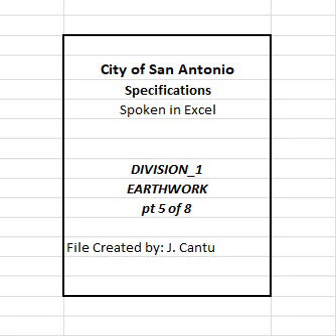5. Measurement. Embankment will be measured by the cubic yard. Measurement will be further defined for payment as follows. A. Final. The cubic yard will be measured in its final position using the average end area method. The volume is computed between the original ground surface or the surface upon which the embankment is to be constructed and the lines, grades, and slopes of the embankment.